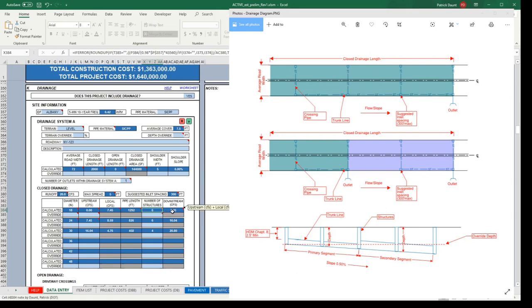So moving on, the downstream CFS is going to just be the upstream value plus the local capacity of that pipe, so the flow that's going downstream of the 18-inch pipe. So this value is then injected into the upstream flow for the following pipe size.